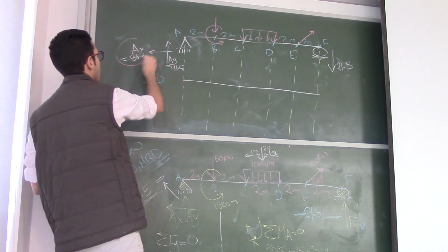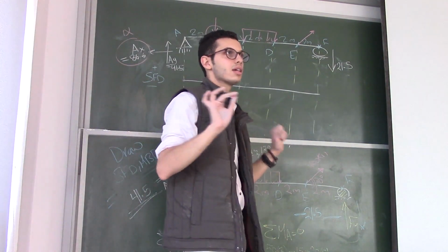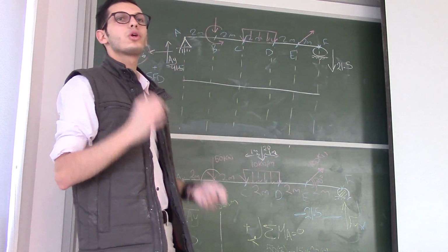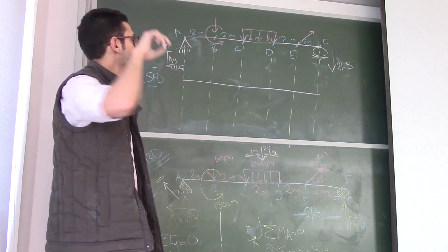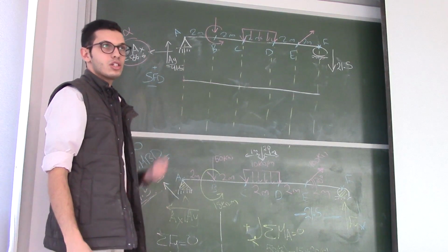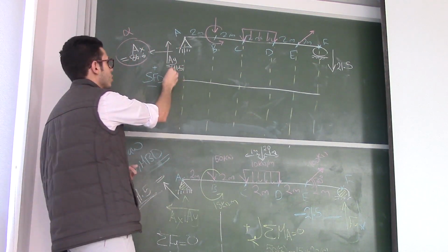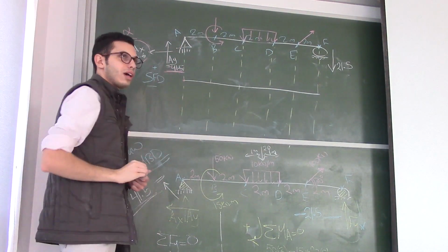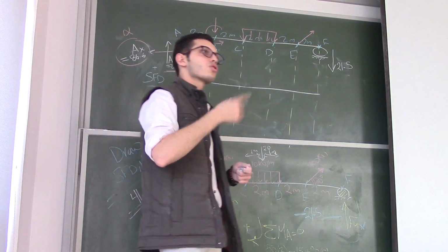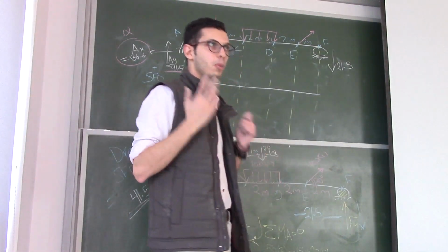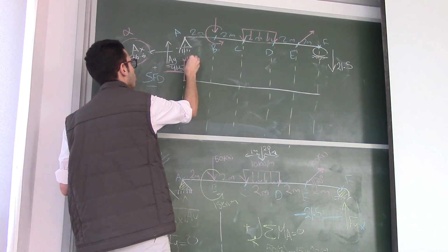So AX does not affect the shear diagram, because it acts on the same axis as the beam. Clear? Now, AY is the shear force. AY is up, and it's equal to 41.5. So according to the table that was written here, if you get a force up, just go up with it. So let's go up with it here to the point 41.5.